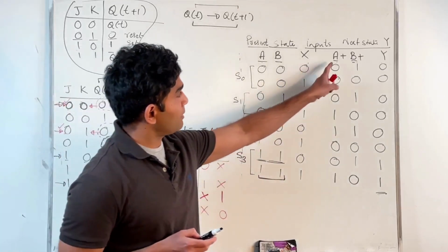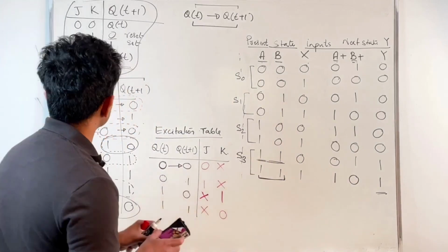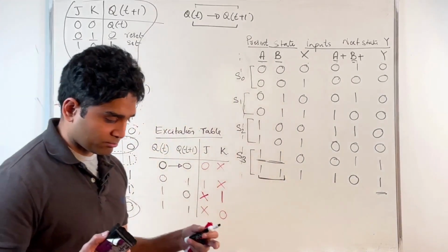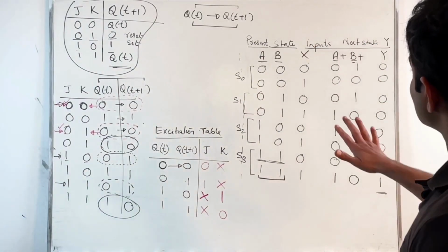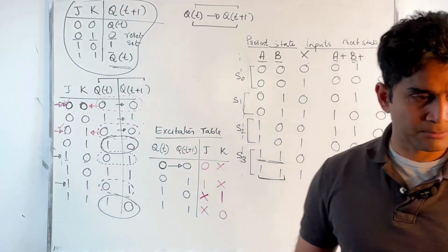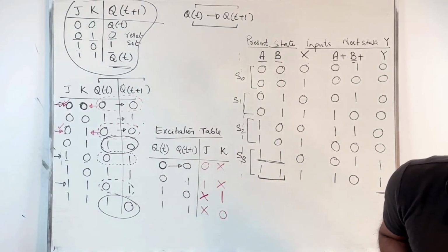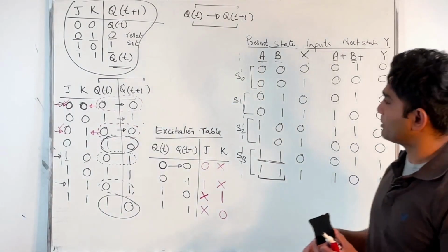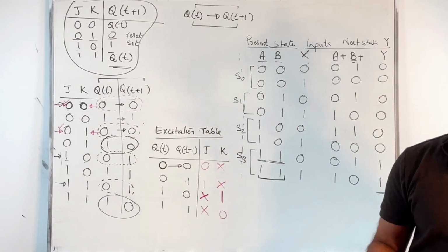I don't have, of course, my A plus B plus represents the next state. So what I will be doing now is, when I want to implement a state diagram or a state machine using the K-maps, I would be redrawing my state table slightly differently. Are you with me until this point? How we derive the excitation table for the flip-flop. So this is the format you will use. This is the methodology that you will be using to derive the excitation table for any flip-flop.